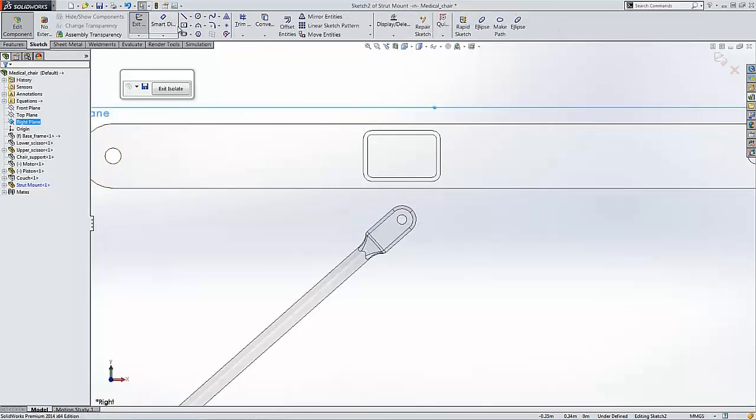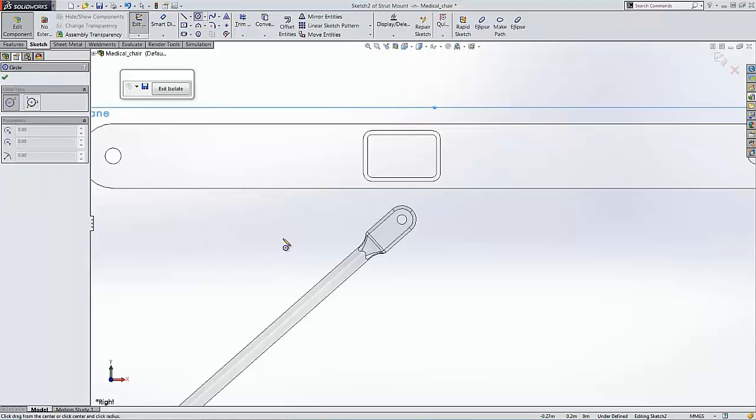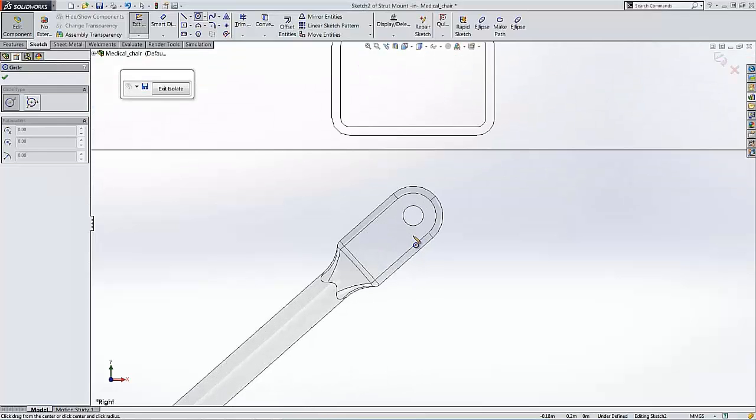Anyway, back to designing my mounting bracket in the context of our assembly. We'll start by sketching out a profile. Now we could use our standard sketch toolbar to select the appropriate sketch entity, but I would much rather use my gesture wheel as you see on screen at the moment. This provides quick access to the same entities by holding down my right mouse button. Hold it down and move your mouse towards the tool you require.